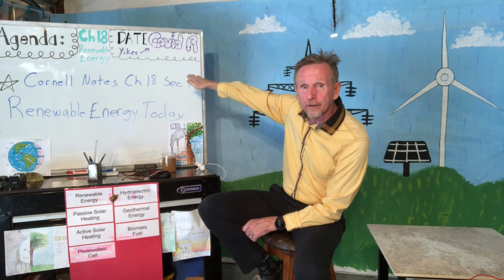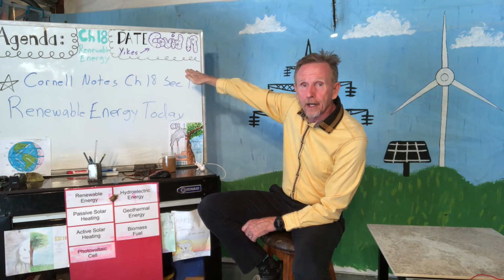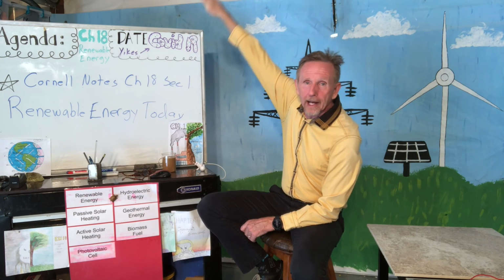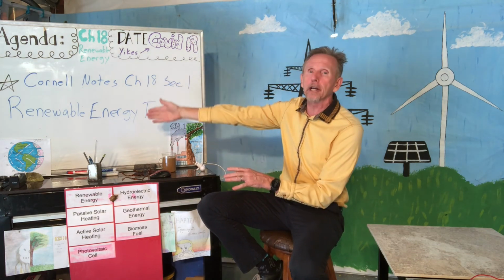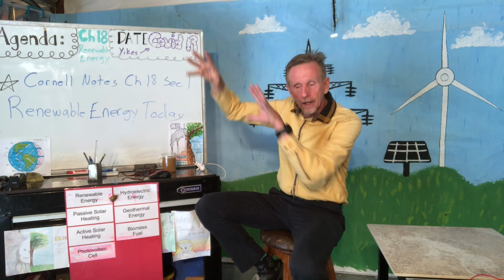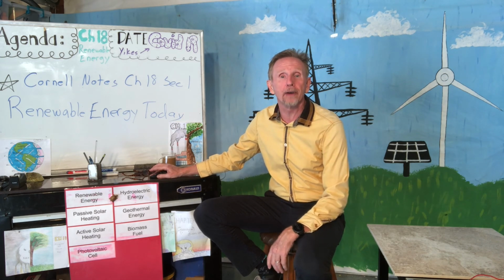If it's in the winter, it's quite low in the sky. You know, spring and fall midways, and in summer it's still not directly overhead. So if it's facing south, it comes up a little bit southeast, the sunlight hits the face of the building and it can warm the building up. We can get some free heat. So passive solar buildings tend to have large windows that face south, and an average household can reduce its energy bills by using a lot of these passive solar features.